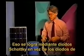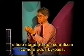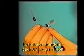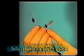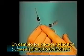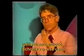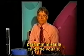One way to do that is to use Schottky diodes instead of the standard silicon diodes that are used as bypass diodes. Diodes that are used as bypass diodes can be silicon diodes. These tend to drop about 0.7 to almost 1 volt. But we don't care too much about that because they're not normally in the circuit. Schottky diodes, on the other hand, drop only about 0.3 or 0.4 volts. Since blocking diodes are always in the circuit, we would use Schottky diodes in that case to minimize the amount of voltage drop that we'd experience.